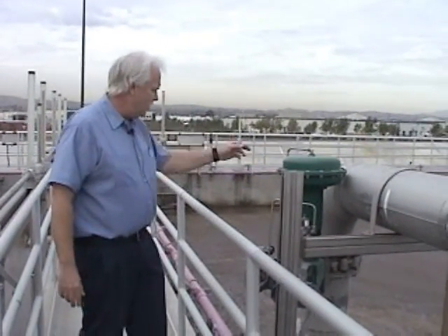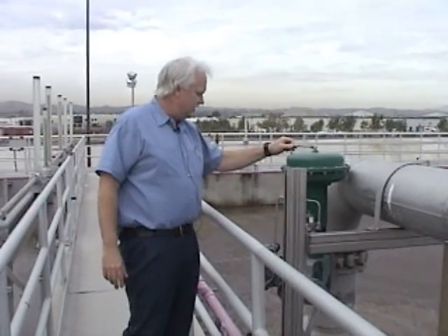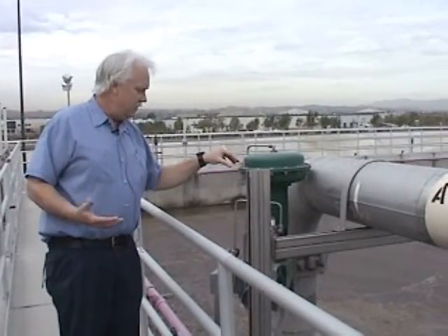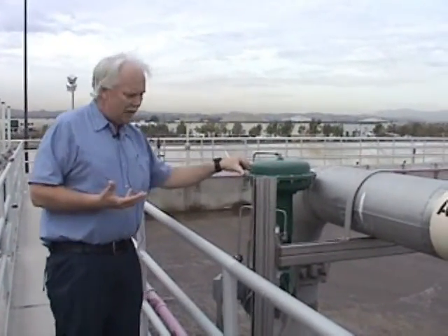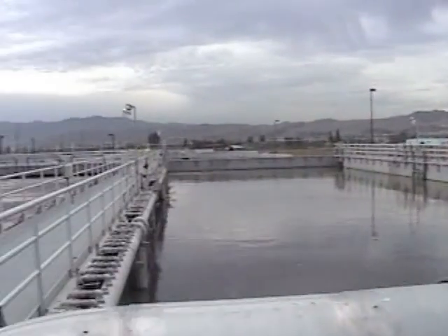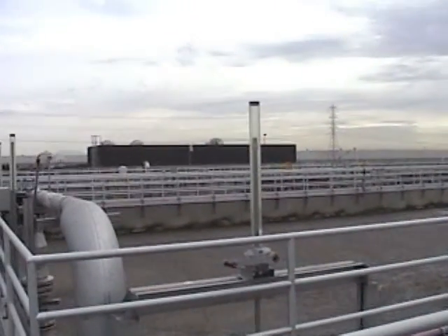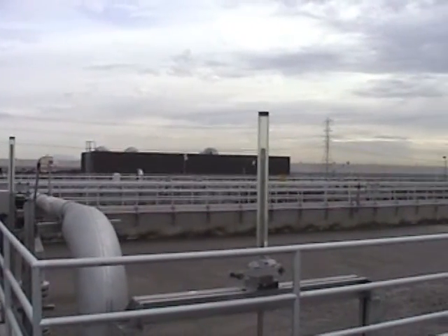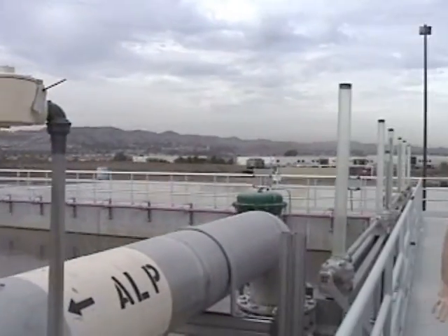I think what's important to remember about this valve is that this is a pneumatic valve. It uses plant air. If you ever have a power outage or something like that here at the plant, one of the things you have to watch for is the Ingersoll Rand air compressors over in Power Center 2. When they're not running, we're not producing plant air, and the lack of air will cause these valves to close.